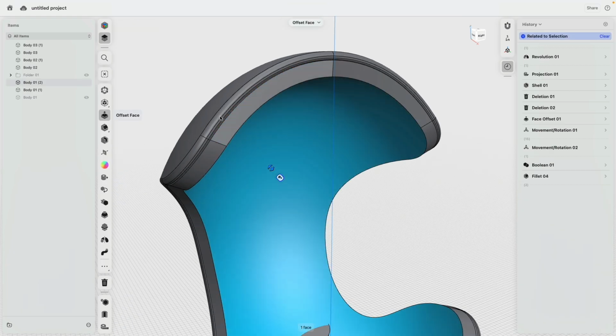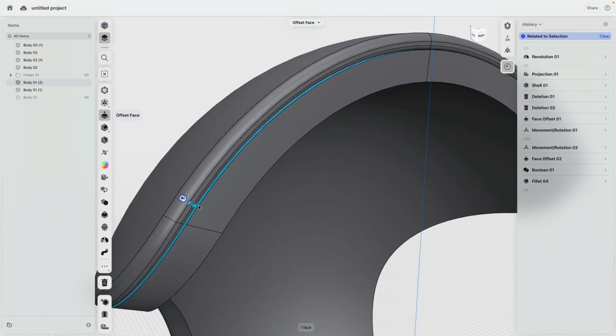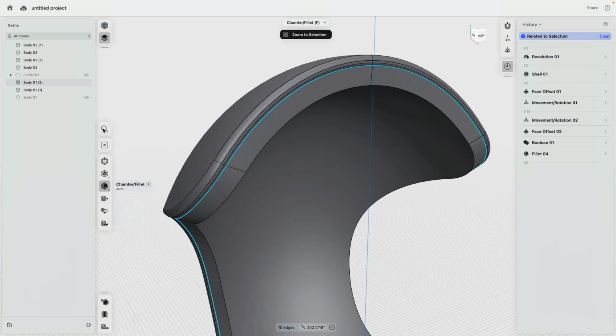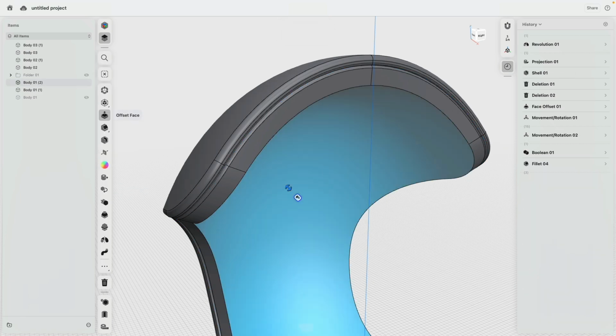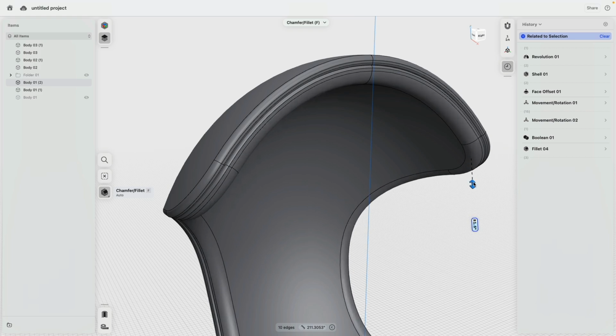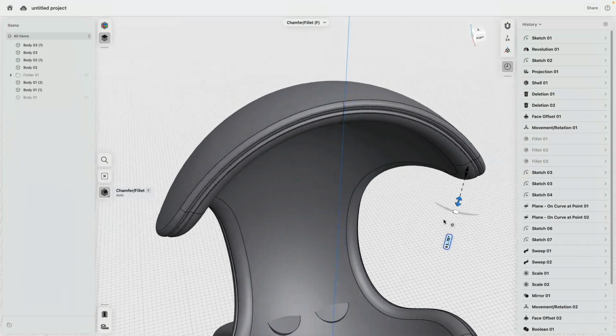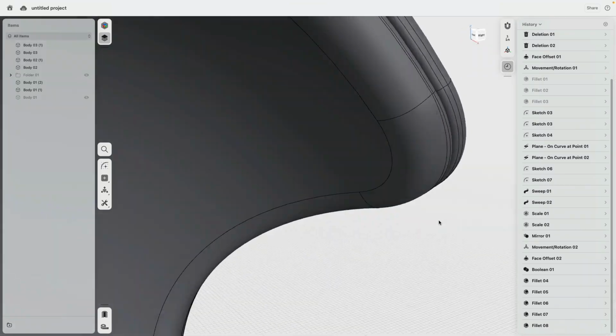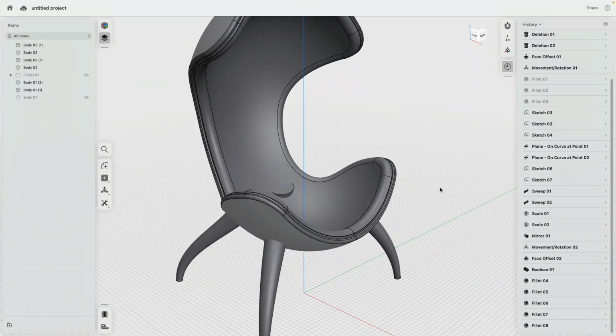And then here I can select this surface and say chamfer fillet 0.25. This surface, chamfer, and then here I bring this down, let's say to there. And I would like here to play a little bit with the tangency value, not the opposite way. Let's say like this. Yeah, so you see this is a little bit straighter. Beautiful. Cool. Okay.